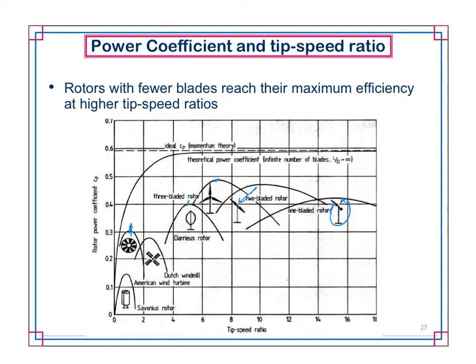That has its highest efficiency at extremely low tip speeds, because if you run too fast, the air that was there pushing the wind is still in the way, essentially. It still hasn't moved on, if that's the right term. So why go with a 3-blade design? There's a couple reasons. The first reason is it has the closest efficiency to maximum out of all the designs, right? But that's expensive. 3 blades is a lot more expensive than 2 blades, which is going to be more expensive than 1. So that's part of the reason.